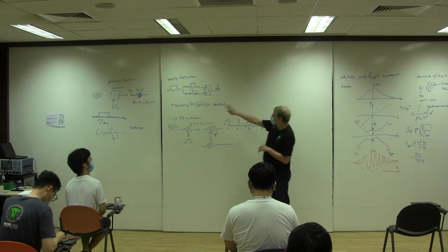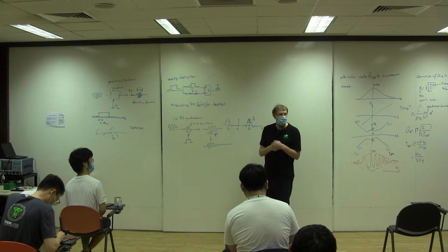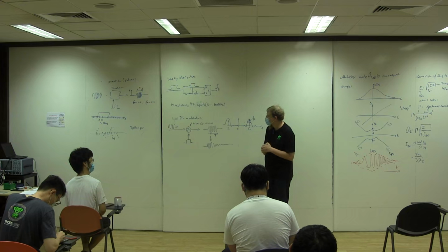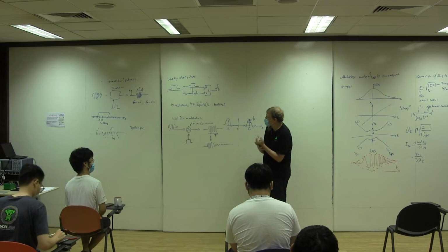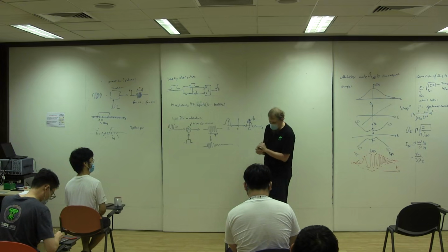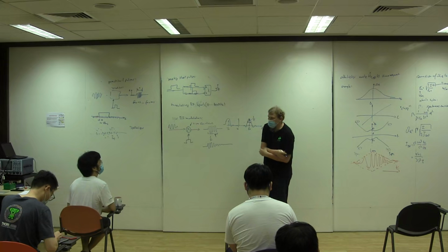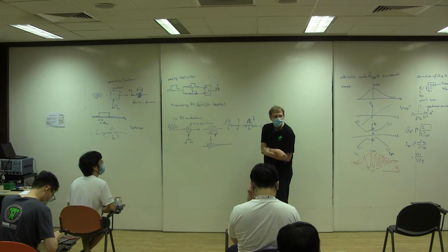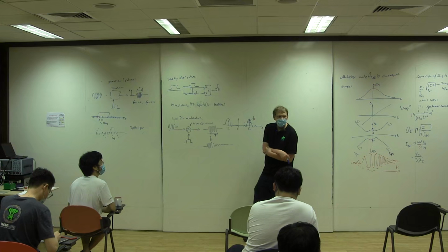These digital pulses have a particular amplitude of 3 volt or 3.3 volt or 5 volt or 1.8 volt or -1 volt, depending on the logic you use, and you often need an amplifier to bring it to the amplitude required by your modulator. That's a bit of a tricky part, but it is so specific that I probably don't want to cover it in this lecture, unless you have a specific question.